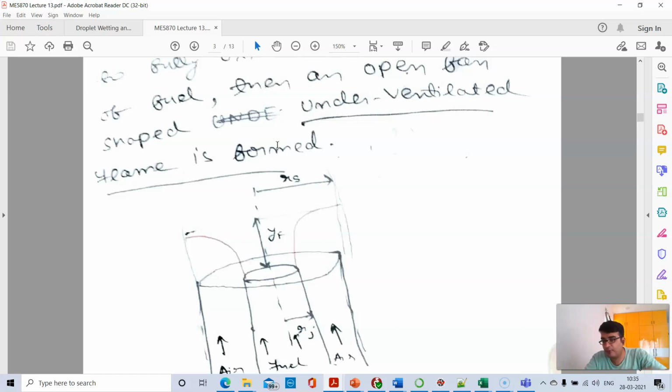It was also determined by where the flame is anchored near the burner edges, where the heat loss increases and the boundary layer velocity becomes equal. So flame speed considerations and heat loss considerations determined where the flame was going to be located. Now here flame speed does not exist, so how do you know where the flame surface is going to be?